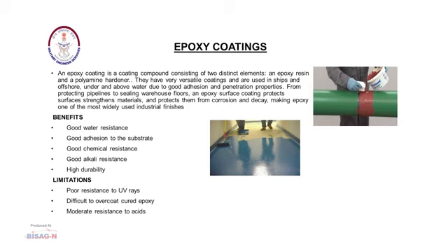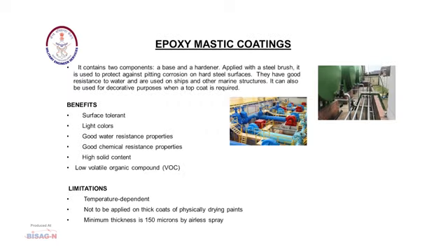Benefits: they have good water resistance, good adhesion to the substrate, good chemical resistance, good alkali resistance and they are highly durable. But limitations are: poor resistance to UV rays, they are difficult to overcoat, moderate resistance to acids. Epoxy mastic coatings.